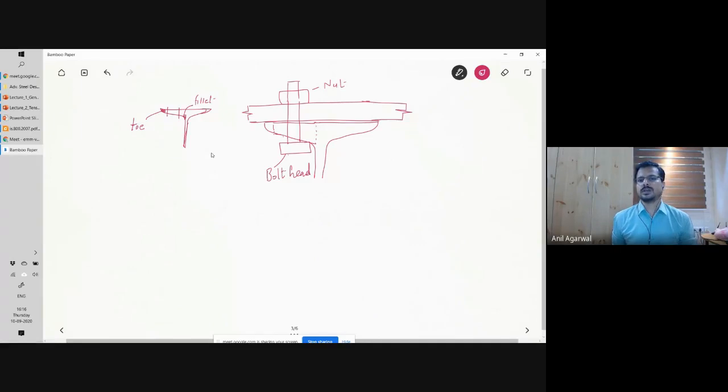So you can appreciate the issue here, right? There are various ways in which you can compensate for it. There are different types of filler plates or washers which have a tapered section, which can compensate for it. You put one such plate here which will fill this space exactly, so that you have perfectly parallel surfaces available at both ends. But that is additional material that you have to keep account of, and also it's not a very elegant design. The major advantage that parallel flanges bring in is in this respect.